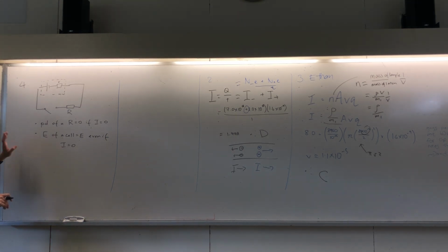However, a battery doesn't work that way. The EMF of a battery is the potential to run a current through a circuit. So it is always there. That means even if I have a battery not connected to anything, there's a PD between these two ends because the EMF still exists in the battery. The battery is ready to convert chemical potential energy to electrical energy anytime, just that I haven't connected the circuit, but the E is there. So case in point is this.